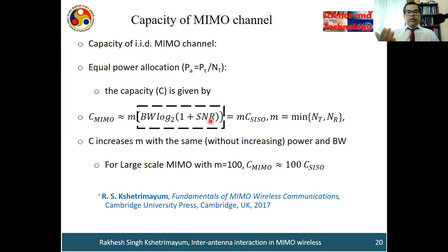One is when you increase the signal power, there will be a lot of interference. That is one of the inherent problems in wireless communication. Interference is the biggest issue. So this is not a good idea. Increasing the SNR or increasing the bandwidth is not possible. And increasing SNR is not a good idea. It has other very important issues like interference, and even the biological effects also.